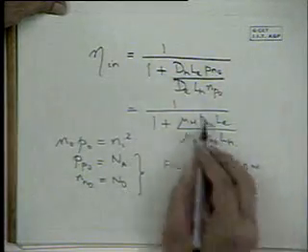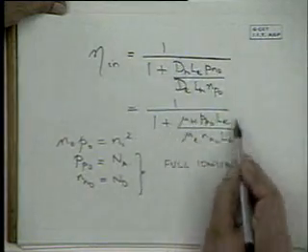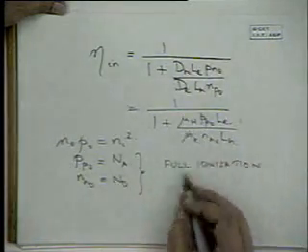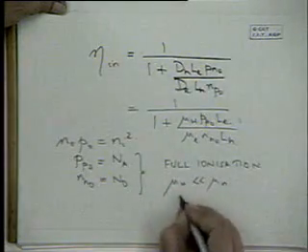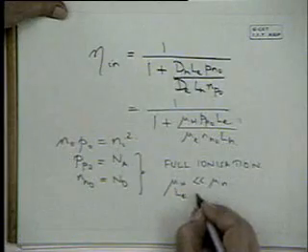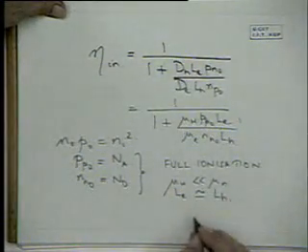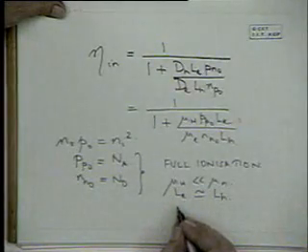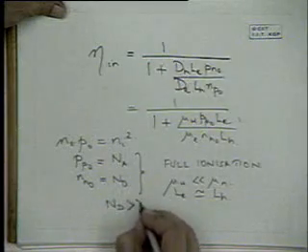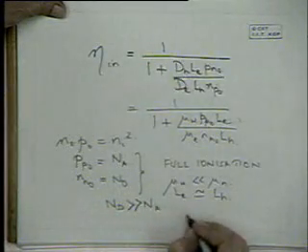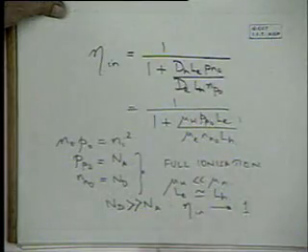We want this factor to be as close to unity as possible, so obviously we want the second term to be negligible. And we know that mu H is usually much less than mu E for most materials. LE is greater than or equal to, we can say it's equal to, LH. So when Nd is much greater than Na, it's an N plus P junction, and the injection efficiency tends to unity.